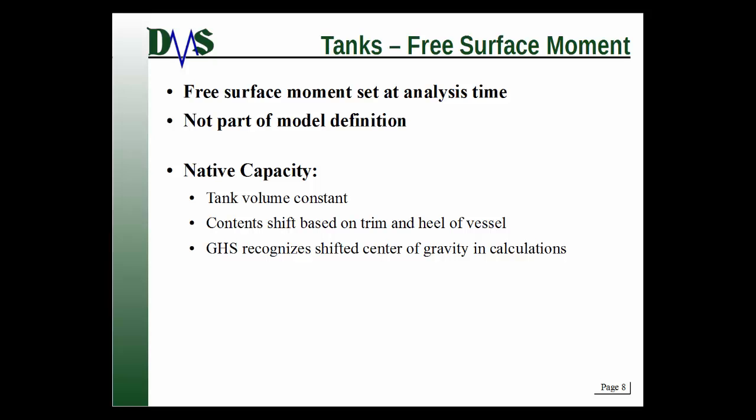So just keep that in mind for some of your analyses, because some of these can become iterative. You tell the GHS that the ship heels over based upon balancing out its moments. Well, the ship heels over, now all the tanks shift, and so the center of gravity is shifted, and so GHS has to rebalance the ship and heel it some more as well. Now, GHS does that, but just keep it in the back of your head that it's an iterative calculation.